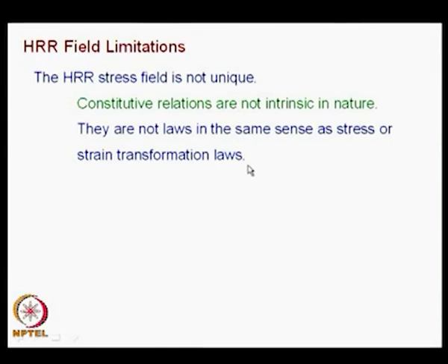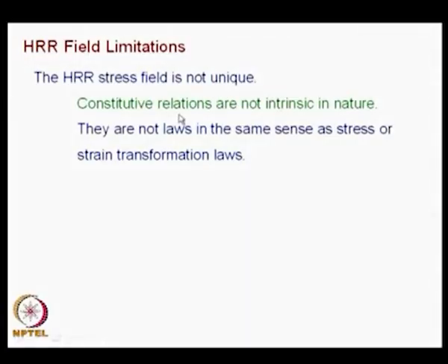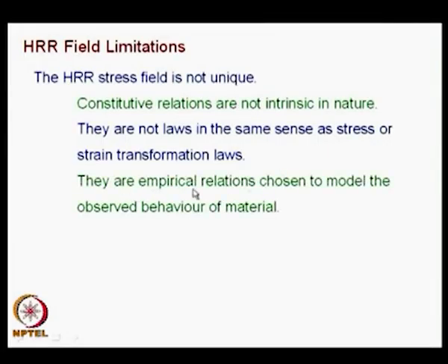The transformation law is definite. If you have a tensor of rank 2 going from one coordinate system to another, it will transform only in this way. In contrast, constitutive relations are not like this. They are empirical relations, you have to keep in mind, chosen to model the observed behavior of material.